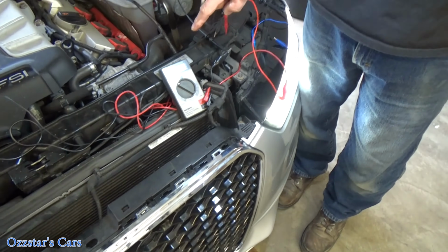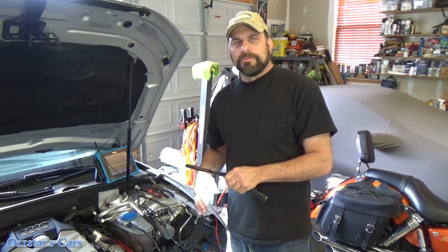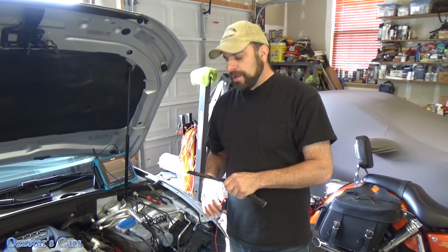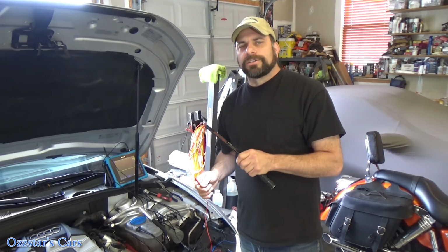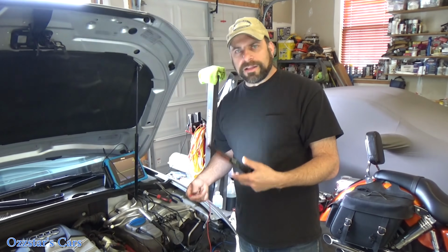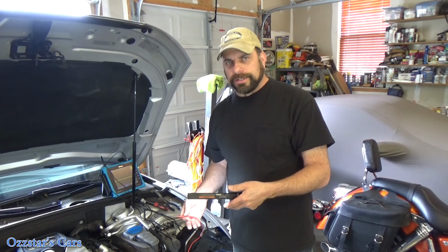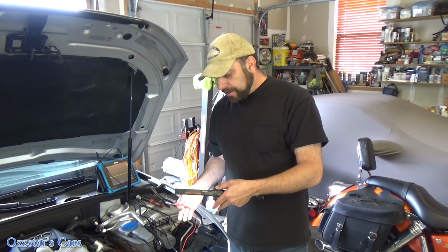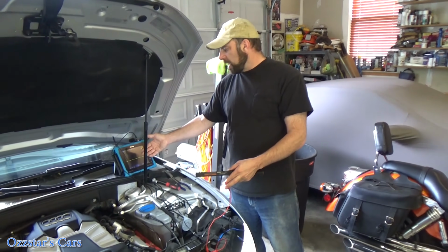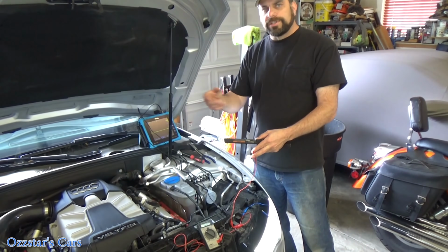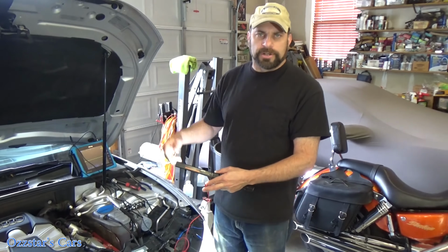The thing is, if you have a bad switch in there, you're pretty much going to get the same voltage. So that's what makes this a little tricky to actually pinpoint what's wrong. Now I like to be 100% sure that I'm not parts changing and throwing the parts cannon at it, but in this case you really can't tell. You have to have an oscilloscope to check the signal. So we want to see those data packs. So next step, I think what we'll do is we'll hook up the oscilloscope and I'll show you that.